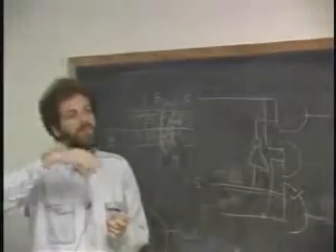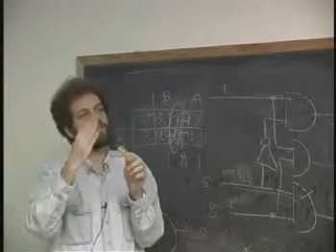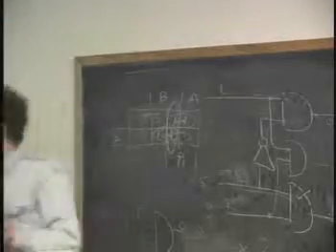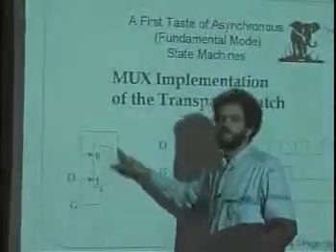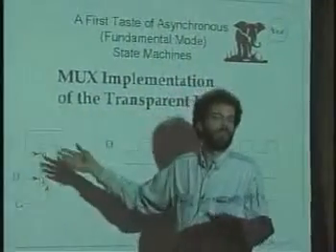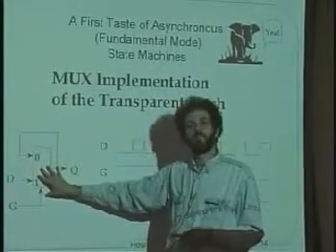If when we suddenly said, okay, switch from being transparent to latching, if during the switch we generated a glitch on the output, then instead of holding on to the high value here, maybe the glitch would start to circle around and around and around. And that would be bad. We wouldn't know where we'd end up. But because it's hazard-free, this circuit will work.